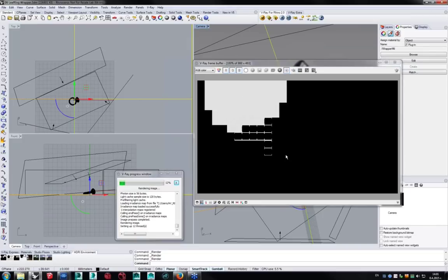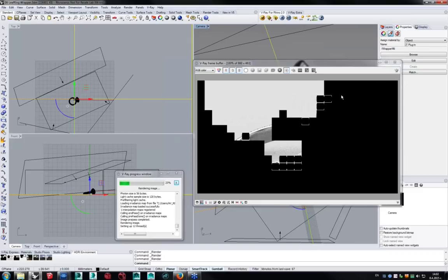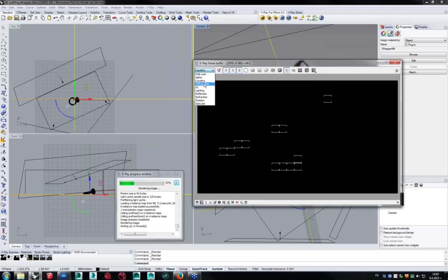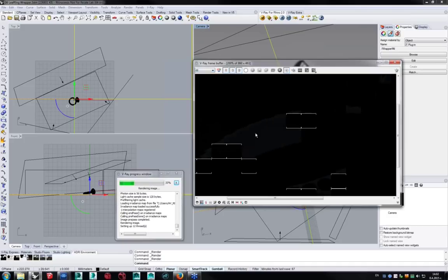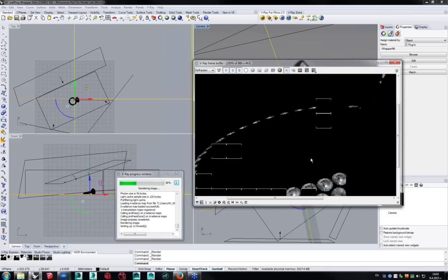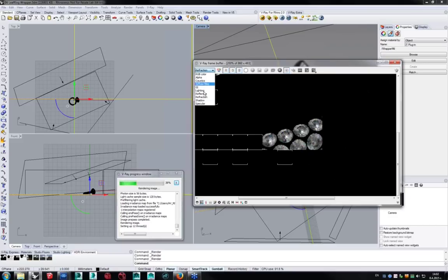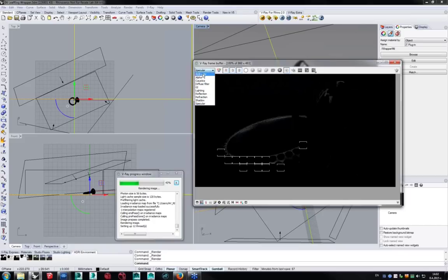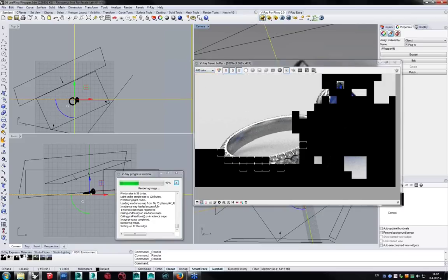So now when you start rendering, you have all the available render elements to use when you go to Photoshop or any other post software to actually be able to change and tamper with any of those. So there we go. This is the alpha, the caustics, which I have disabled, the diffuse filter, the reflections. You can see the GI, the lighting. This is the reflection, refraction, shadows, and of course the specular. So with all these render elements, you'll be able to do that.